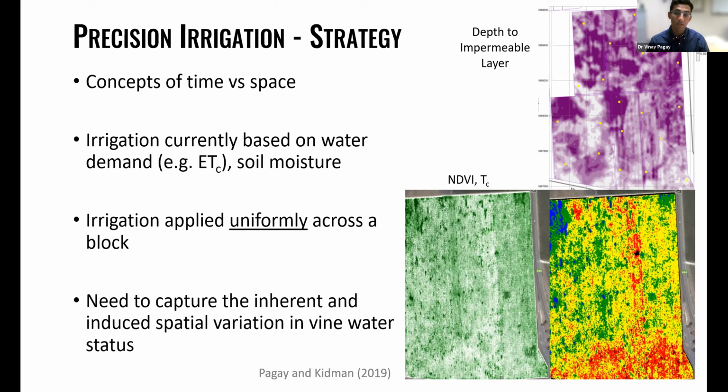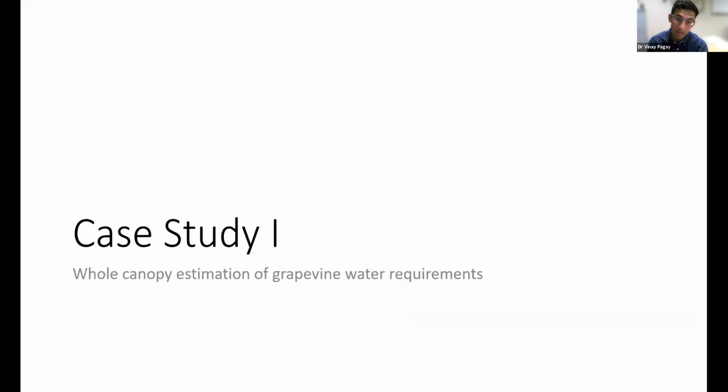The other motivation for this is the placement of any sensor, whether that's a soil moisture sensor or a plant sensor. Getting a spatial map of variability across a block will allow you to then place sensors strategically in perhaps the weaker zones or the more stressed zones and perhaps the wettest zones. And then that allows you to start zoning your irrigation system, so valving, and then starting to optimize, essentially not putting a single irrigation level on across your block, but putting on a split irrigation level based on variations that have been predetermined through remote sensing, as we've shown here in this image.